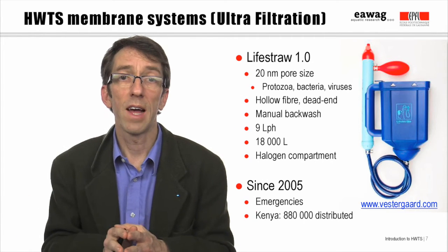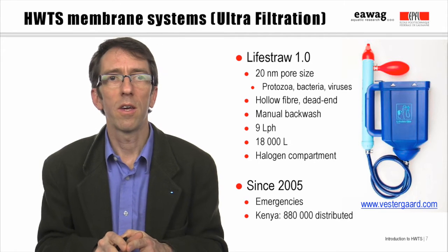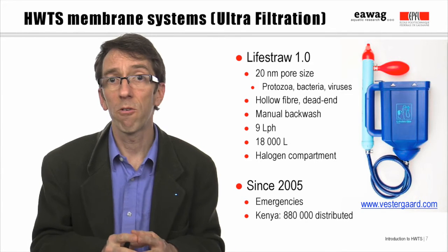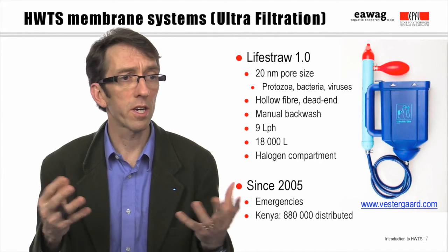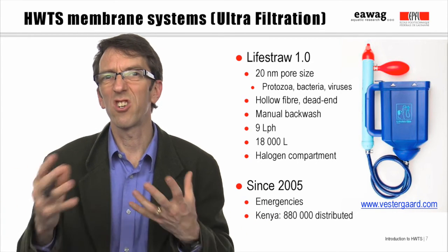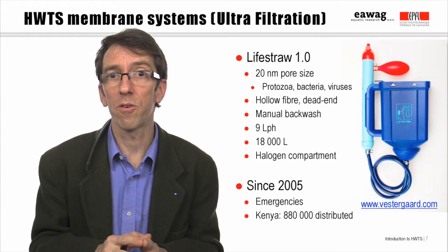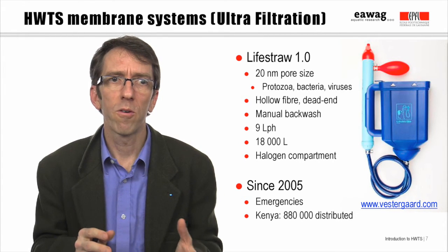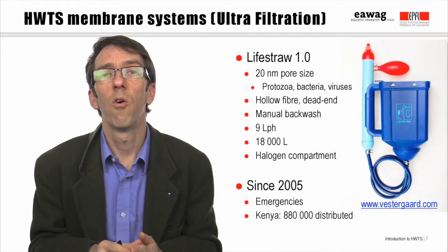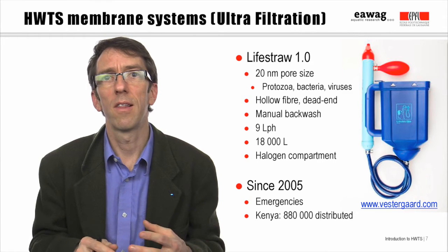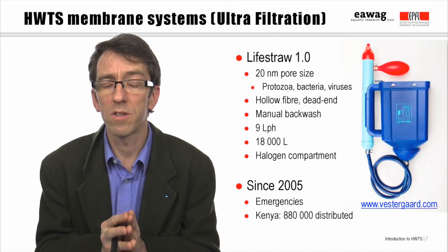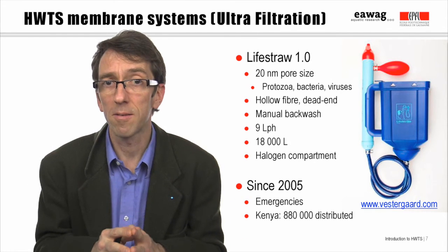There are many examples of household application of membrane filtration in high-income and middle-income countries. Typically, reverse osmosis or nanofiltration systems could be installed in the kitchen. They would require electricity and usually an additional pump to generate the pressure to pass water through the membranes. However, there's increasing development of applications using ultrafiltration or microfiltration membranes that use less pressure to treat the water and can even be applied in some cases without electricity in low and middle income settings.